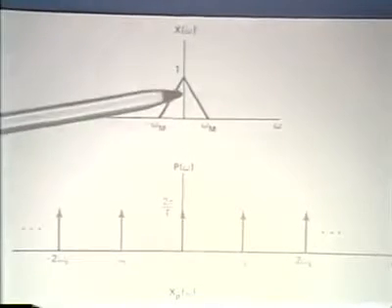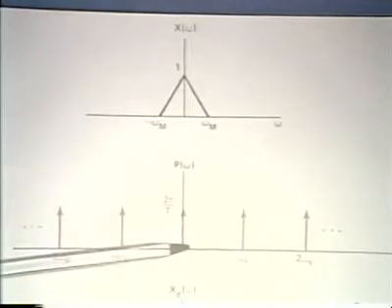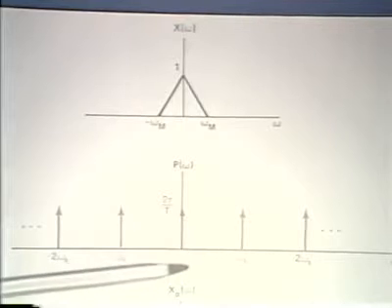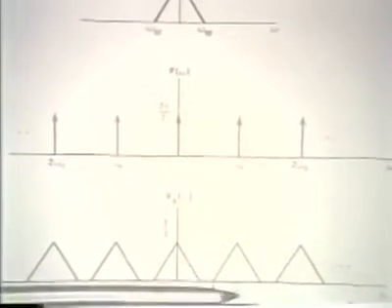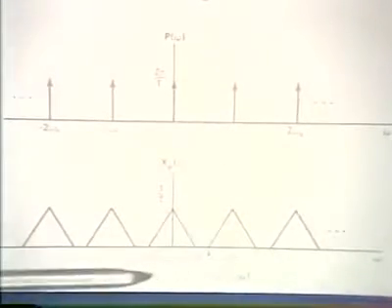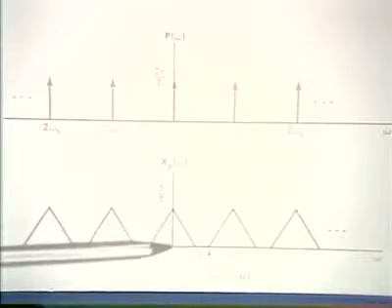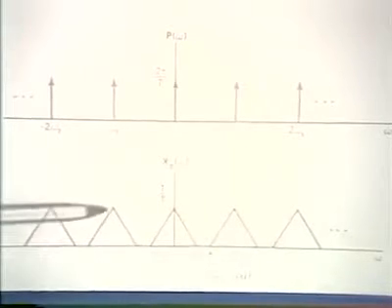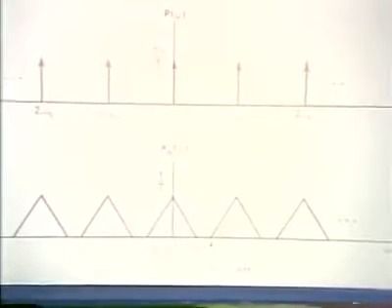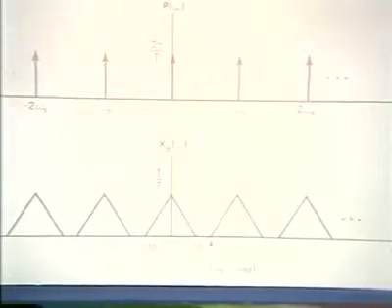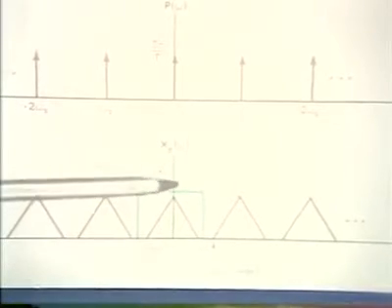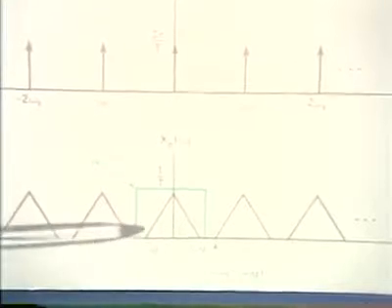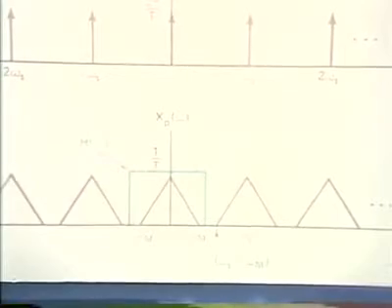The convolution of these two is the Fourier transform, or spectrum, of the sampled time function. And so that's what we end up with here. Then, as you recall, to recover the original time function from this, as long as these individual triangles don't overlap, it just involves passing the impulse train through a low-pass filter, in effect extracting just one of these replications of the original spectrum.